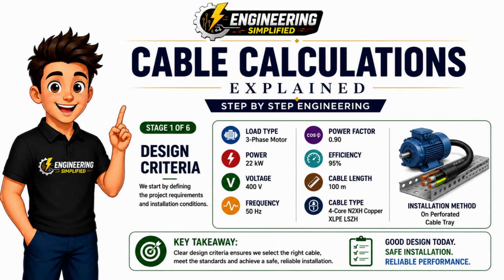Let's get started. Every engineering calculation begins with good design information. For this example, we'll be sizing a cable supplying a three-phase motor rated at 22 kilowatts. The motor operates from a 400-volt, 50 Hz supply, has a power factor of 0.9 and an efficiency of 95%. The cable length is 100 meters, and we've selected a 4-core N2XH copper XLPE LSZH cable installed on a perforated cable tray. These design criteria form the foundation of every calculation that follows.